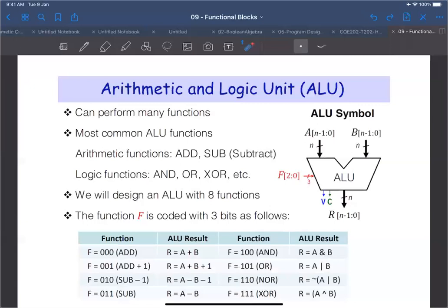Usually we don't use the ripple carry adders that we have seen in the previous unit, but we use something called a carry lookahead adder, or an even more sophisticated version. A carry lookahead adder is very expensive. It consists of many more gates than the ripple carry adder, but it's very fast.